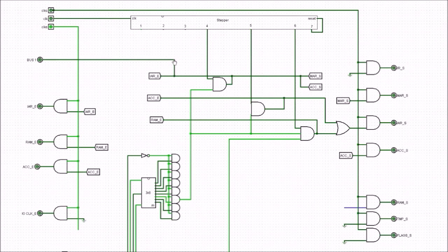But the next point in the RAM is going to contain the data for this JUMPIF instruction, and that data in effect is the actual address that we want to jump to. So we don't want to pick up that particular byte as the next instruction, because it isn't; that's the data from the previous instruction. So we need to add 1 on to ensure that the next time we come round we're actually pointing at the proper address in RAM.